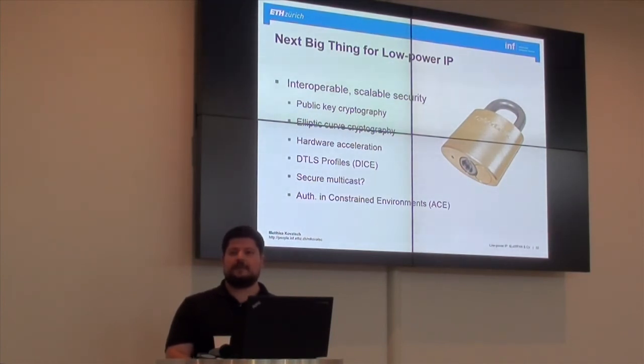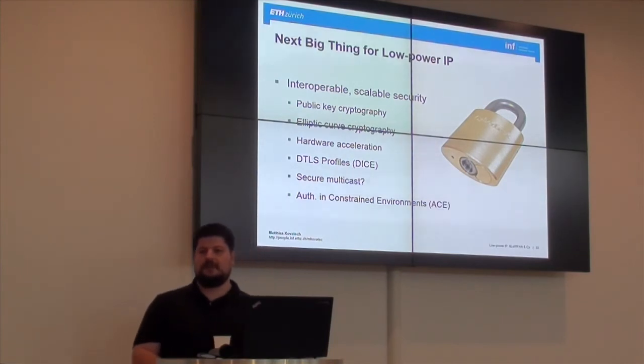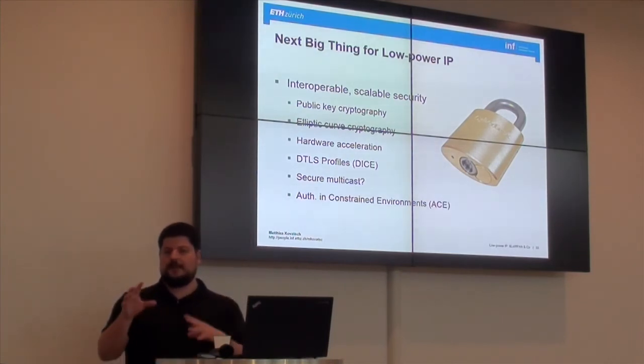And so you run Contiki on it? You can, there are several software options as well. So I plan to run Contiki. The things were ported to this system on a chip. They had this Texas Instruments development kit for the 2538, so it works for that. There's the OpenMote OpenWSN implementation, which is basically the foundation for open source 6TiSCH. It's from Berkeley, they developed that. It comes with CoAP and also some Python libraries to communicate with it.